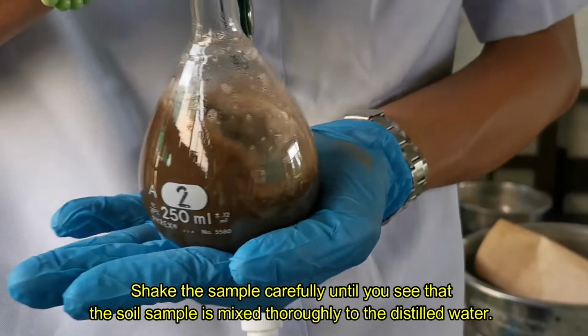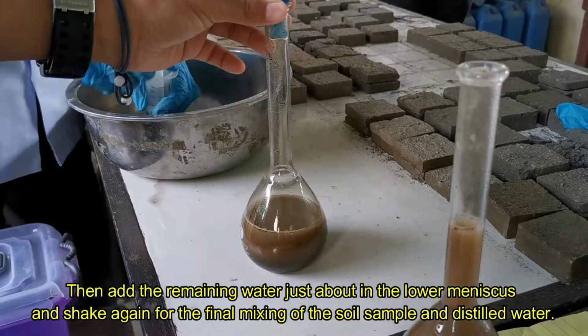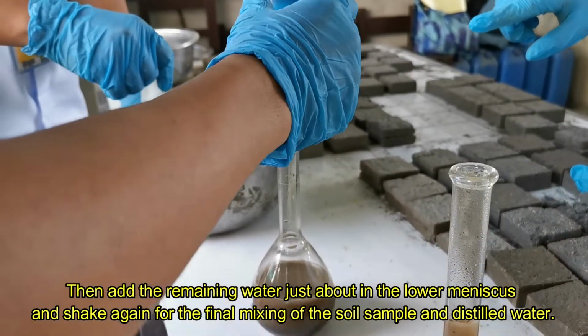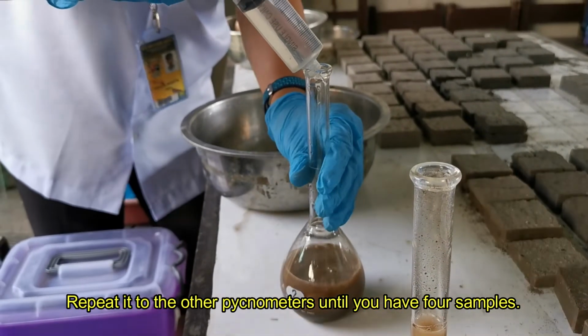Shake the sample carefully until you see that the soil sample is mixed thoroughly with the distilled water. Then add the remaining water up to the lower meniscus and shake again for the final mixing of the soil sample and distilled water. Repeat it for the other pycnometers until you have 4 samples.